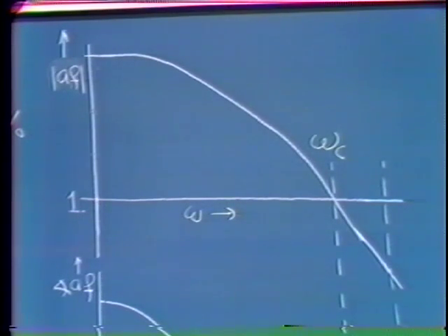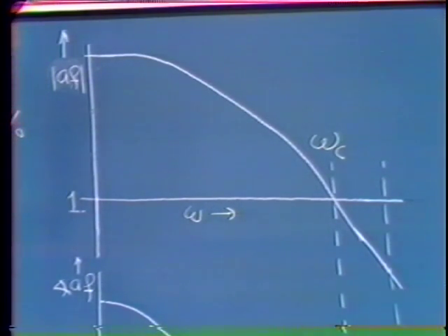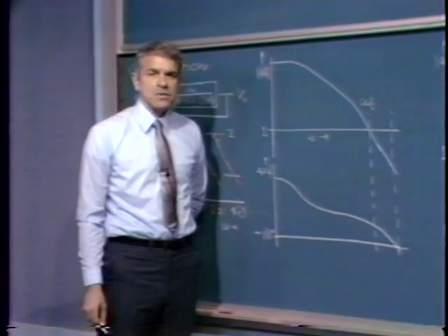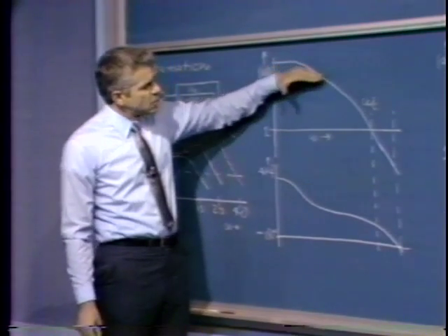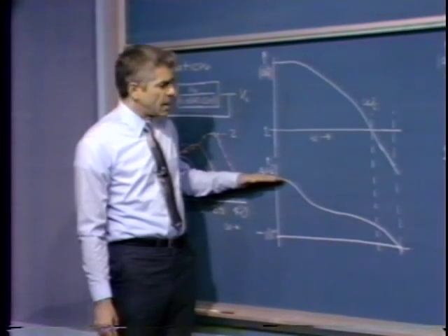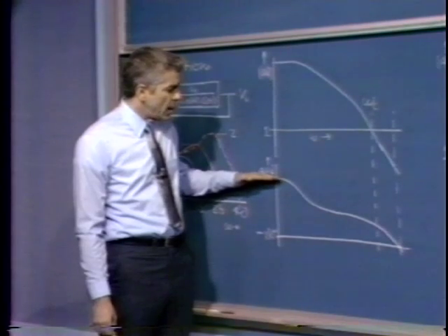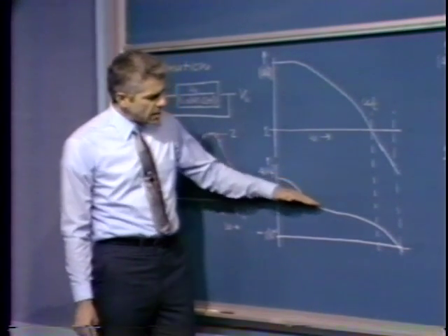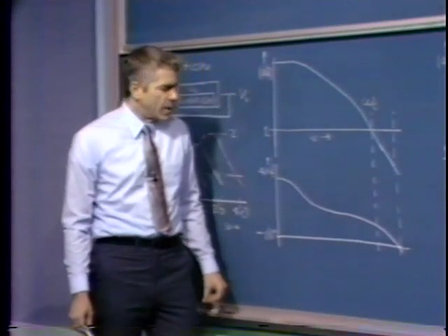I'd also then like to define the phase margin of the system. And to determine the phase margin, assuming we have a stable system, incidentally, for any of this, we really have to go back and check via Nyquist test whether the system is stable or not. But we've very rapidly learned to recognize familiar patterns. If we have a well-behaved, maybe typical kind of system where the magnitude is a monotonic decreasing function of frequency, the angle starts out possibly close to 0 degrees, or in the case where our loop transmission includes an integration, which is a fairly common case in mechanical systems, the angle of the AF product would start at minus 90 degrees, and then again drops off and goes through minus 180 degrees only once. It doesn't wiggle back and forth around the minus 180 degree line.